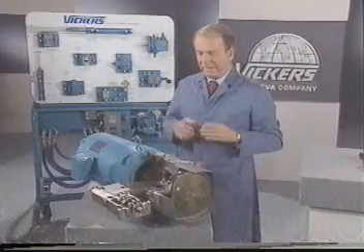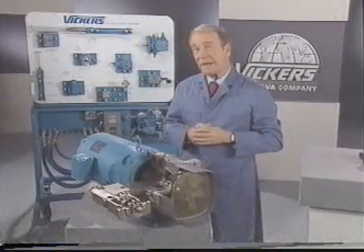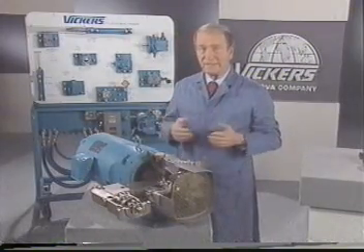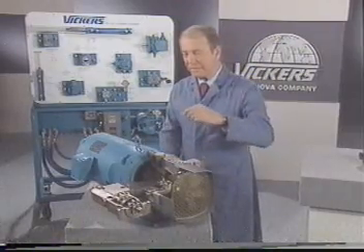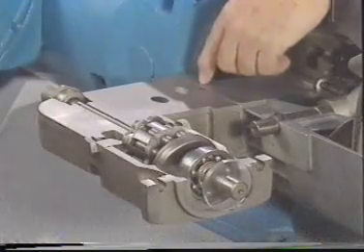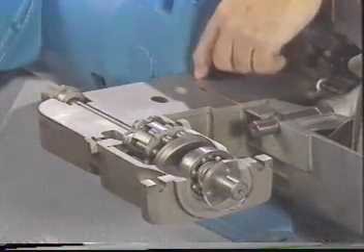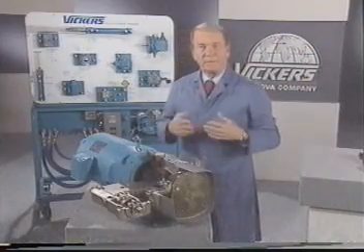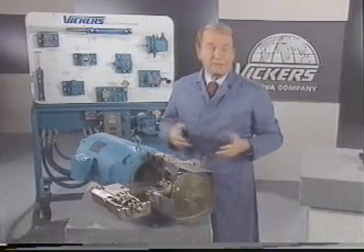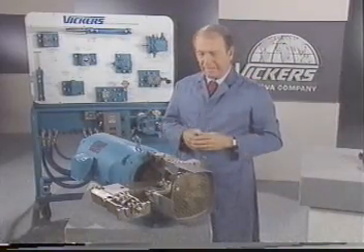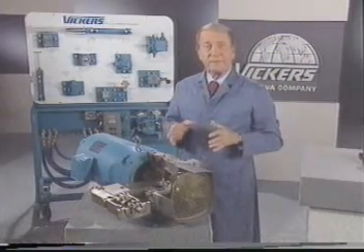If our application happened to be in a remote or hazardous area, a hydraulic motor could be removed and mounted separately, with lines running back to an adapter plate at this point. In this way, the pump, electric motor, and other components could be located out of harm's way. Now, let's move from our cutaway to a working unit.